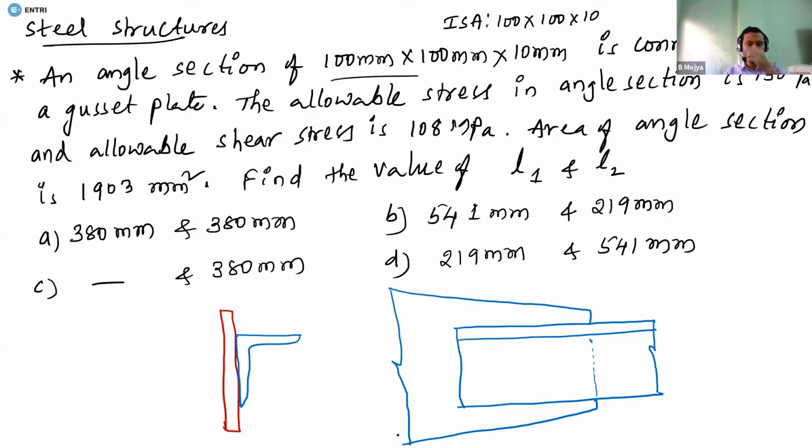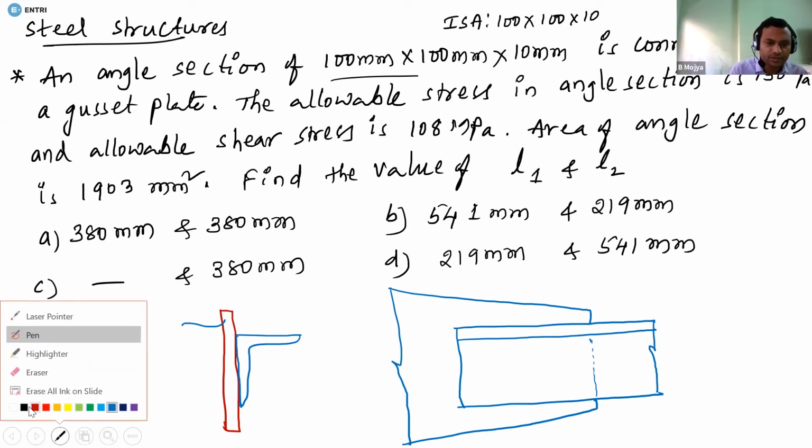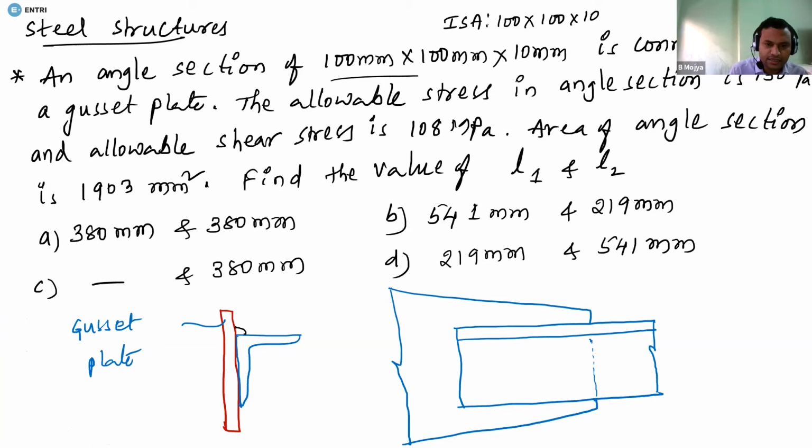Continuation like this. Okay, so this is a cassette plate, and the welding is done. Let me show the welded part. So welding is done on this side and also on this side. The welding which is done is with a 5 millimeter weld. Okay, welding is 5 millimeter. And this height of the leg is 100 millimeter.